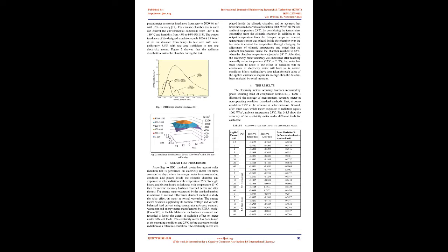[6] In 2018, Erkata Yandri used 16 units of halogen lamps of 50 W each. The lamps were fixed on an aluminum frame with dimensions of 430 mm x 390 mm x 1000 mm. The distance between the light surface and the test area was 32 cm, giving a maximum non-uniformity of 9.7%.